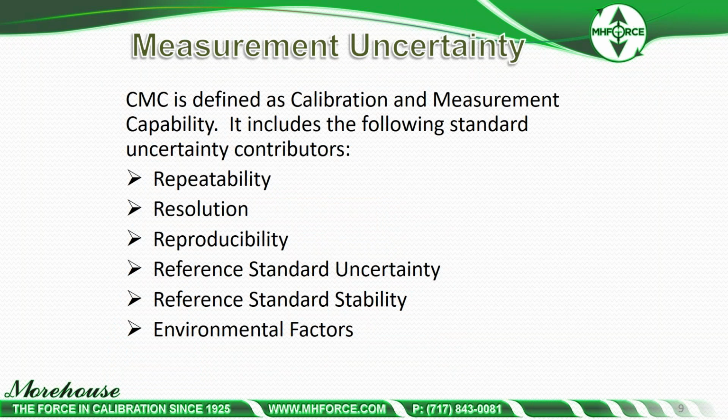It's usually defined somewhere on a scope. The accreditation bodies come out and accredit people. They specifically want you to do a CMC, which is a calibration and measurement capability. I borrowed this from A2LA R05 because I like this. It's the best I've seen. It's not just throwing every load cell specification or every manufacturer specification in there, which may not mean anything to how you're using the instrument, where these do.